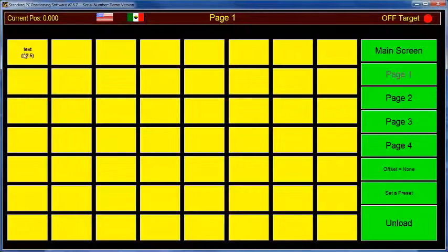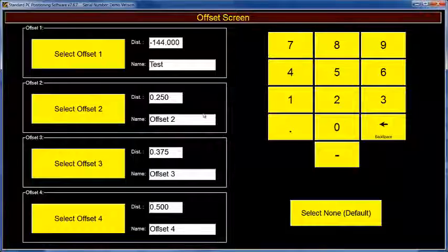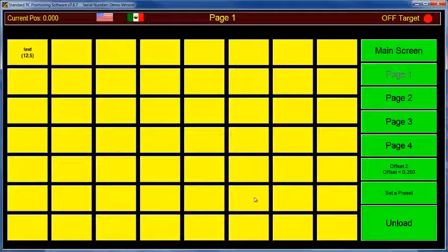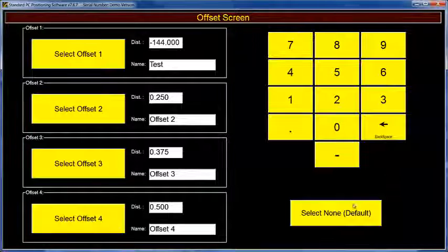and click Enter. And now when you click that button, the RazorGage will move to that position with one touch. And you can define each one of these. You can also apply the offsets just like we talked about. It tells you here which one is enabled. You certainly want to keep an eye on that if you're using offsets, because anytime you use an offset, if you forget you have one turned on, you can cut some bad parts.